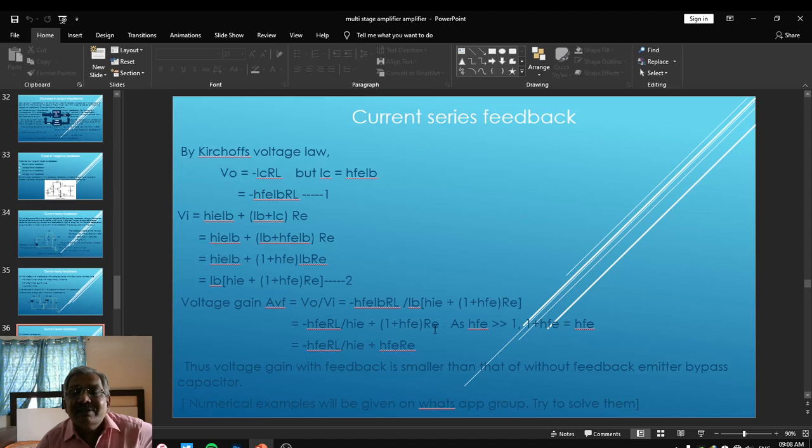This indicates that as HFE is very much greater than 1, we can write 1 plus HFE is equal to HFE. We are replacing this 1 plus HFE only by HFE because the value of HFE, beta, is very much greater than 1. Therefore, we can write the voltage gain AVF is equal to minus HFE RL upon HIE plus HFE RE. We have replaced this by only HFE. Thus, the voltage gain with feedback is smaller than the voltage gain without feedback.